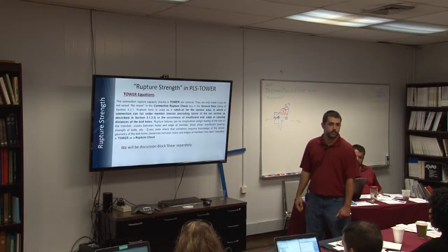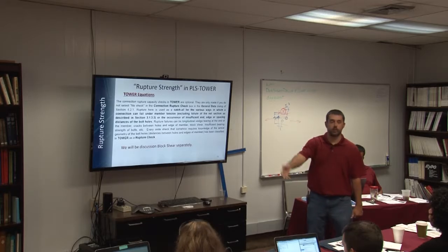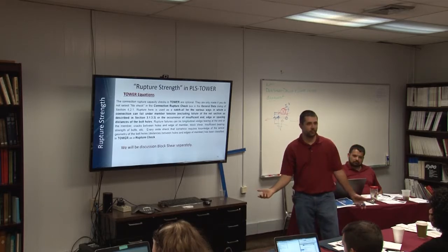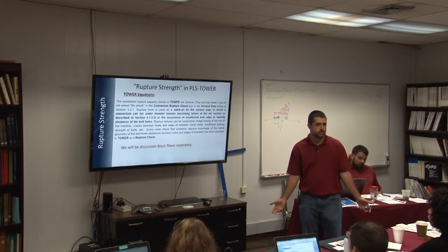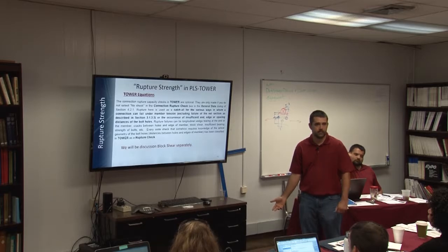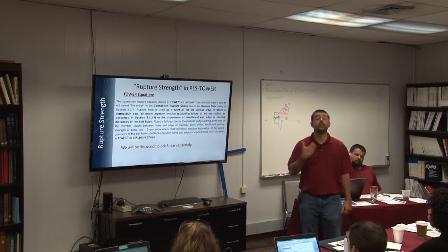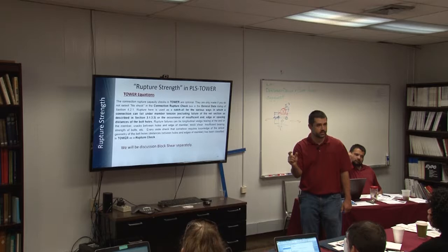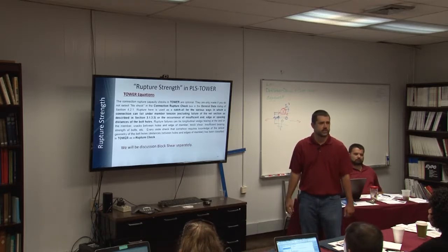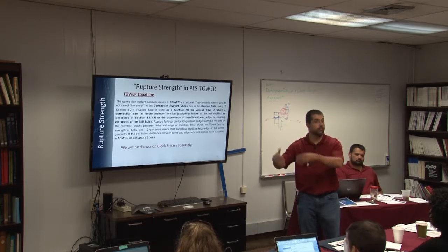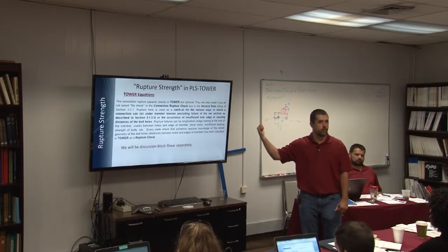Has that code been around a long time? Well, all of those were part of the manual of practice, which was best practices for how to define bolts and connections. So did you find that typically that was being adhered to on a lot of these or not? Yeah, I feel like in most cases, if you get into really, really old towers, the end distance might be shorter than what's typical. But a lot of time, like on all your drawings from the 60s and 70s at least, there's a standard end distance, 1 1/4 inches or something along those lines. That meets these. Okay. It all meets these.